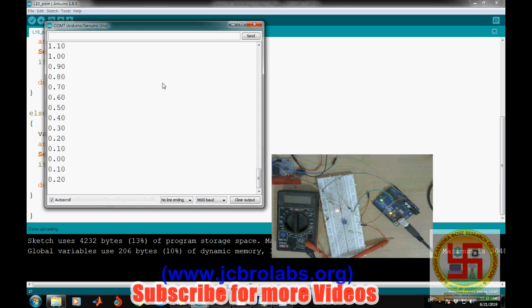Or similarly, if you connect any DC motors to the driver, you can vary the speed of that particular DC motor, slowly increasing, and then slowly decreasing. Okay, so this is how we can use this PWM method to generate a variable analog voltage at the specific pins of this Arduino UNO, and the same can be used for speed control of DC motor as well.